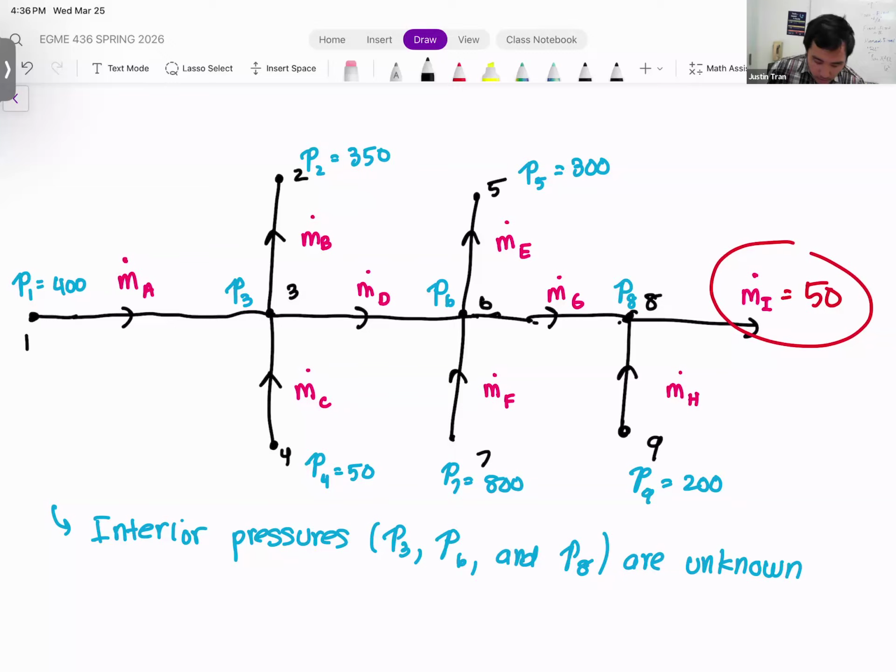And so if you look at our system here, our pressures are defined at the nodes of the system, right? And then in between the nodes, we've defined the mass flow rate. So the mass flow rate is going to be our surrogate for the velocity. In other words, we have velocities and pressures defined at different locations in our system. So this sets up a very perfect staggered grid. And so it's the perfect way for us to apply our SIMPLE algorithm.